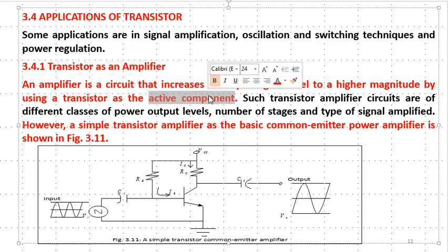In electronics engineering, we have two categories of components. One is called active components, and the other is called passive. The active components are those components that can accept a signal and change its shape by either amplification or changing its nature from AC to DC. But the passive components cannot change it. The only thing they can do is pass the signal by either attenuating or allowing it to pass, depending on the level of their resistance or the level of their impedance, if they are reactive components.